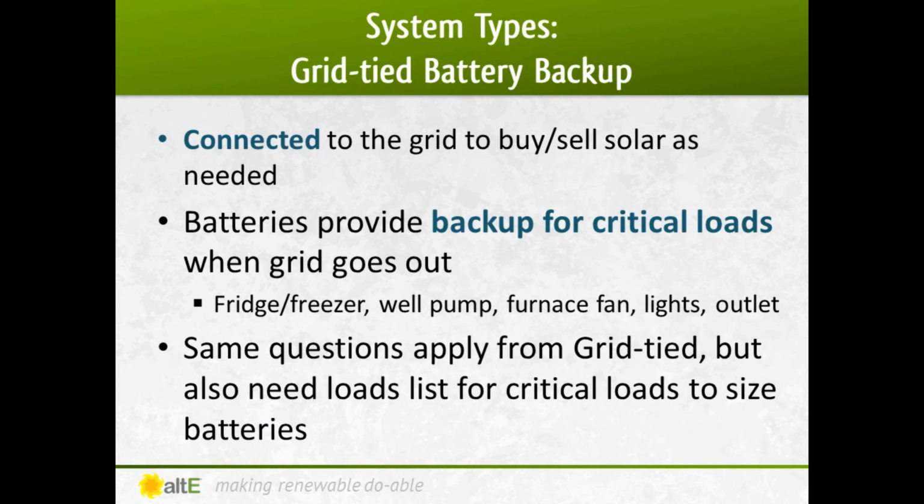When selecting a grid-tied battery backup system, you have to ask yourself all of the same questions as with both grid-tied and the off-grid systems. Remember that you now have the added expense of batteries, so it will be a more expensive system than just a straight grid-tied. You'll also have to do a loads list on your critical loads to determine the correct battery bank and minimum size solar array to recharge your batteries during a power outage.